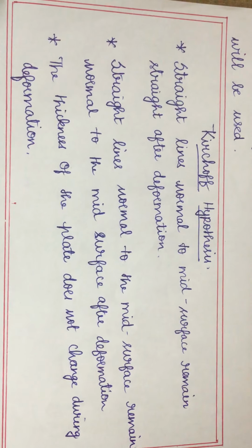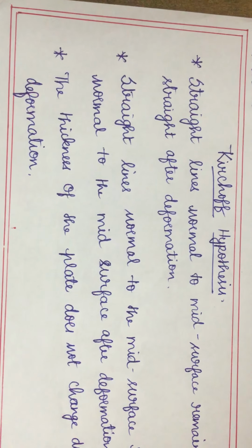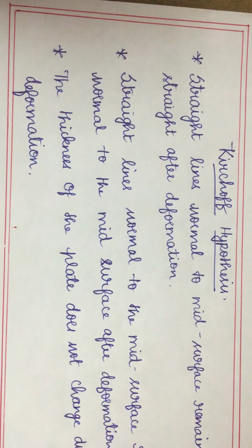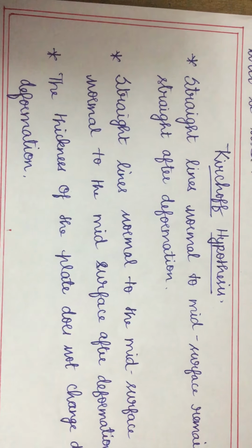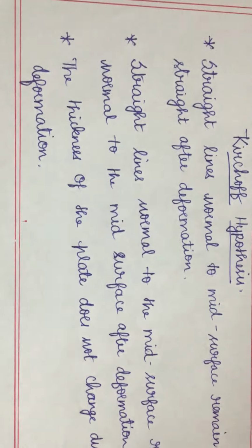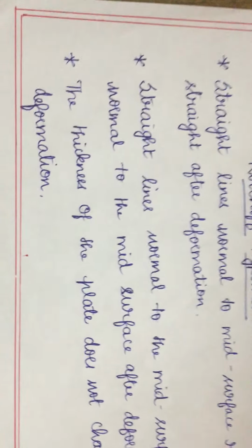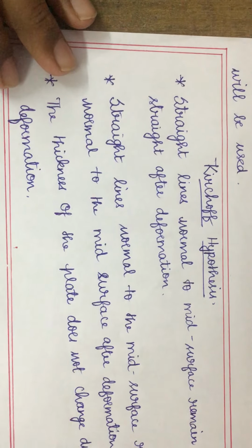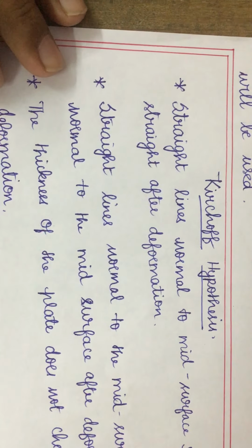The thickness of the plate does not change during deformation. If you deform a structure, its thickness will not change. So these 3 points are called Kirchhoff's hypothesis. When a question is asked in this topic, it is always recommended to write these 3 points, because these are the 3 points with which we will be deriving the stress relation of a laminate and a lamina.